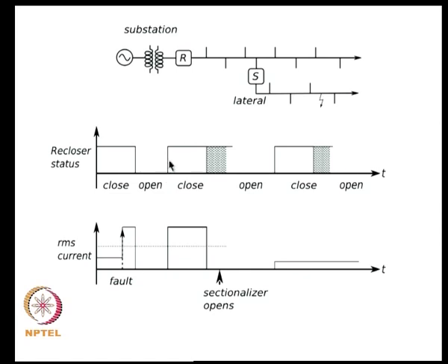During your first reclose cycle, you end up with now a second pulse flowing through this particular sectionalizer, and then the recloser opens. So, when the recloser opens, essentially the sectionalizer would count now 2 cycles and lock open.